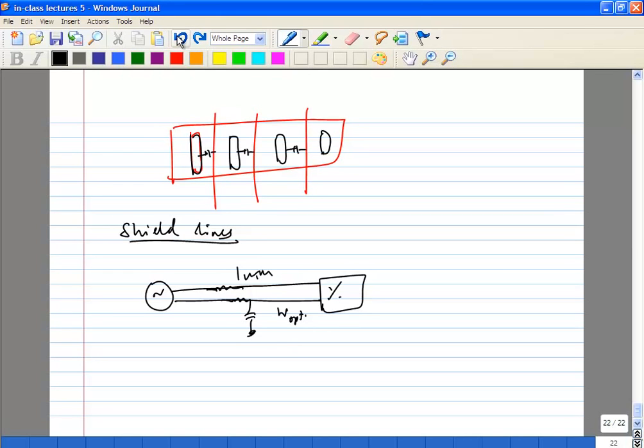Now the next question is, if they're going from the VCO to the divider, they're going to be very sensitive lines. Do you want to add a shield for them? So let us say you add a shield on both sides. What happens? Now you have some extra capacitance to the shield apart from the substrate. You have the capacitance of the substrate already, and you are basically adding extra capacitance. So now you need to space them out wider.